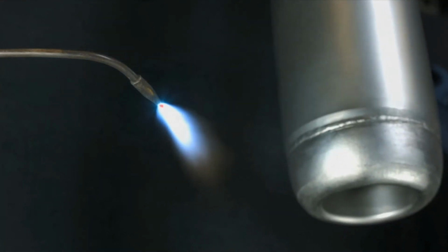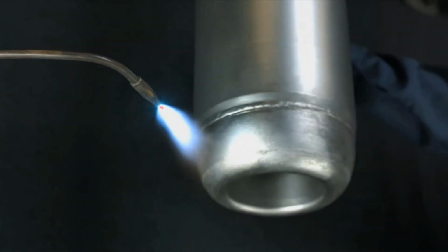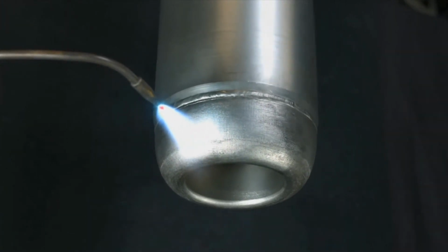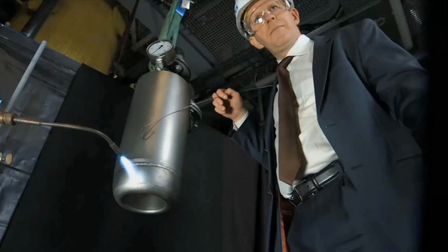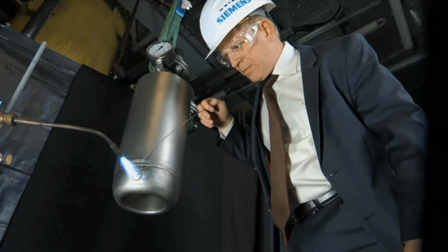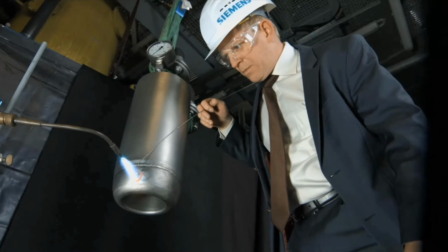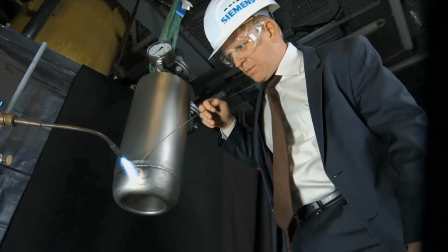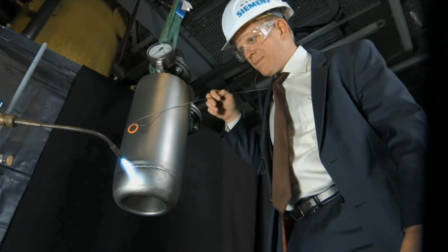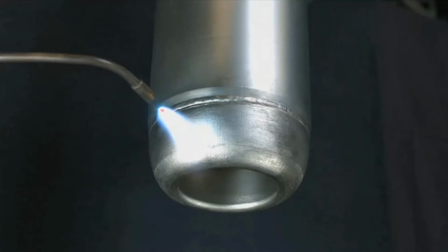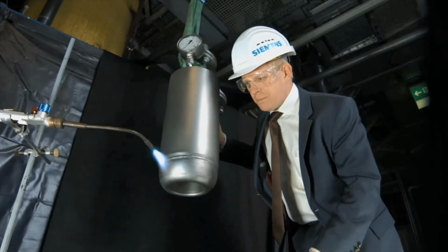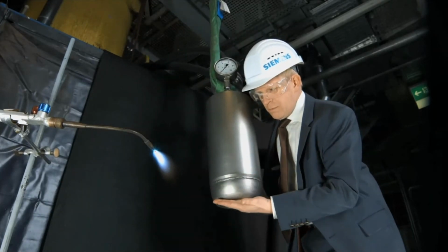The goal of the project was to reimagine this high temperature burner system used in a fuel refinement process. It was a thermochemical conversion process that burned the messy leftover reactants at an extremely high temperature to extract the fuel. The temperature in the chamber is above 1300 degrees Celsius, higher than the melting point of the metal in the part. You can see that there has to be a complex network of cooling to prevent this burner from melting. Otherwise, the gentleman here wouldn't be able to touch that without burning his hand.